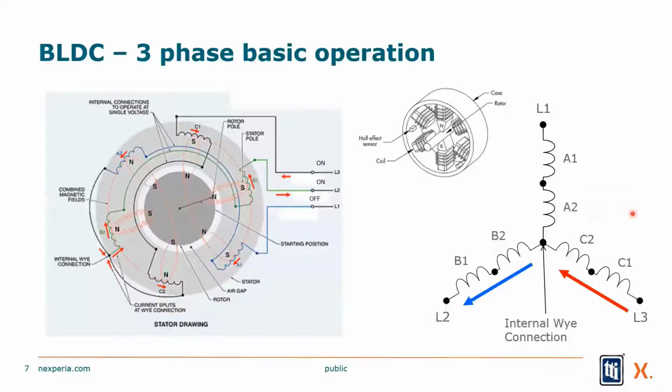How do I hook them up? Here's the wiring inside the device. It just looks a little complex, but it really isn't. Inside the motor, I've got the spinning permanent magnet with its north and south pole on it. Here are the coils around the outside. What I want to do is make each one of these coils in turn go from off, or from north and south to south and north. And then I just simply walk that pattern around.